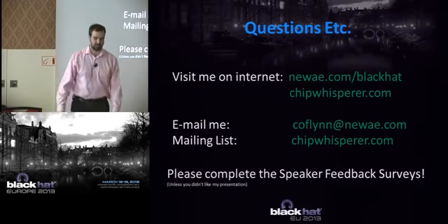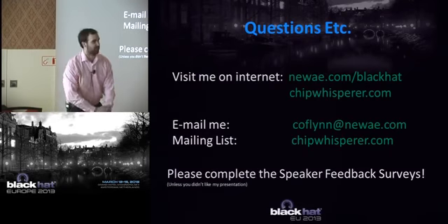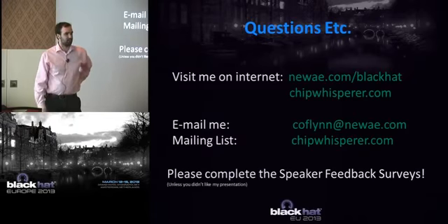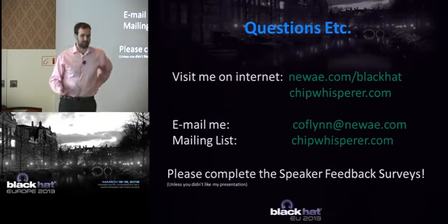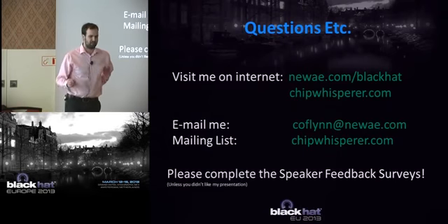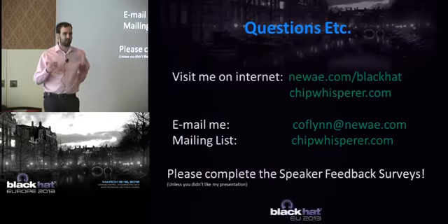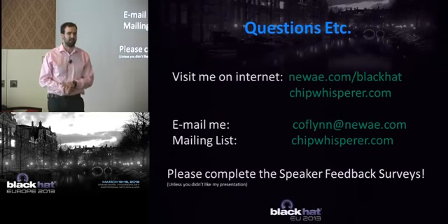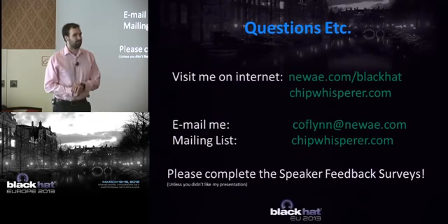Okay, so the question was whether there are chips with asymmetric crypto to look at. I don't actually know. I've only really focused on symmetric, to be honest. I know, for example, the XMEGA only has symmetric cryptography in hardware. You may have to go to actual smart card devices to get that. I know Atmel makes a few security chips, which aren't smart card chips but small 3-pin devices that I believe, I'd have to check, might be RSA.